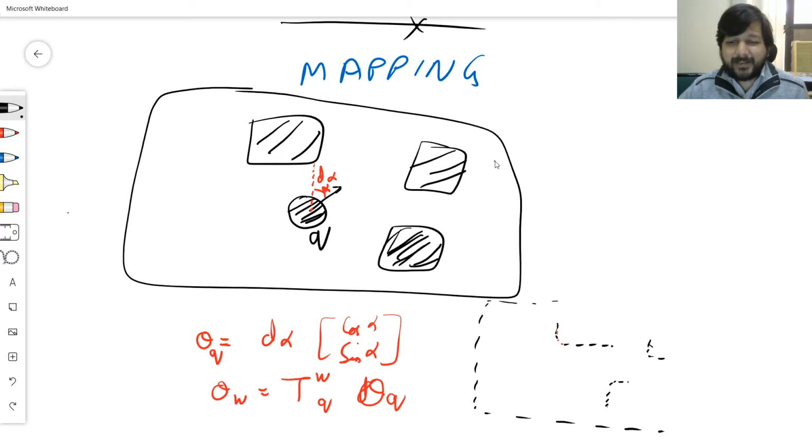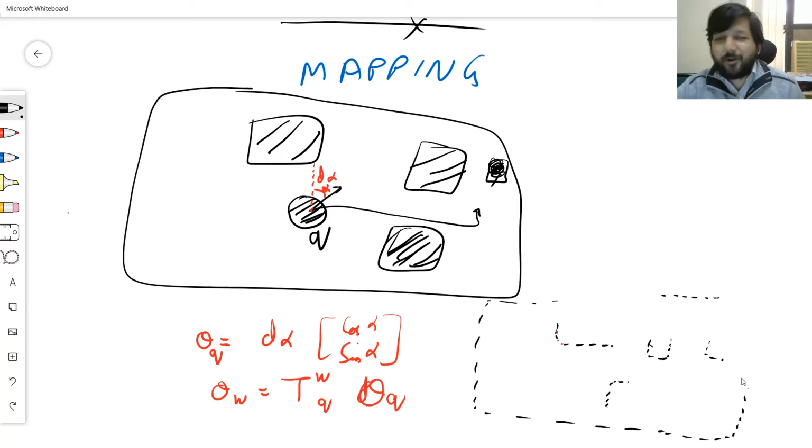So now let's have an obstacle here as well, and let the robot travel around over here and take this image. So it'll actually take this image and it'll be able to see all these things. So I keep on putting all the dots into the image. There is one caveat though. Sometimes you believe that there's an obstacle at this position, sometimes you believe that there's no obstacle at this position. So the same point will be reported multiple times. Sometimes there's an obstacle, sometimes there's non-obstacle.